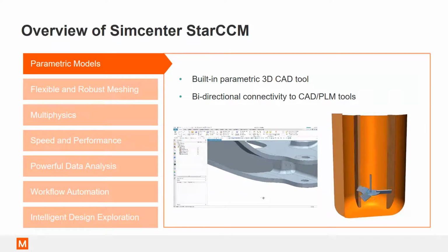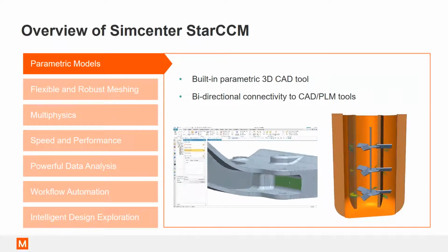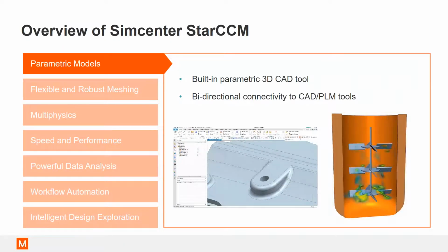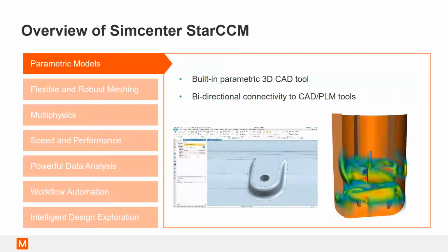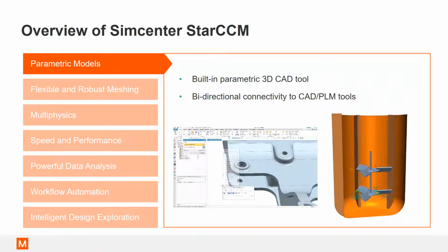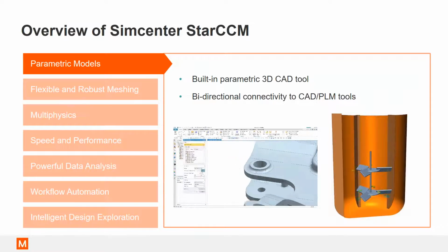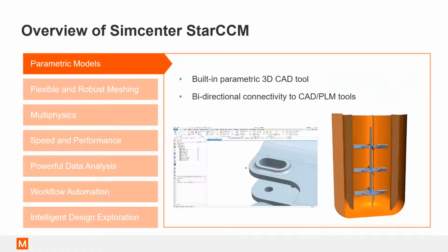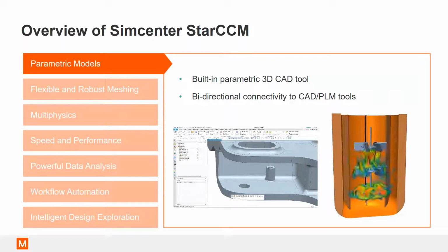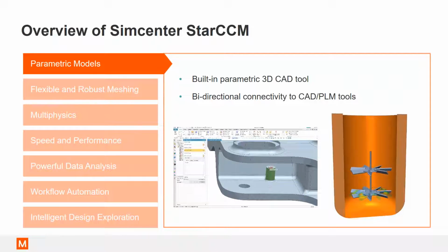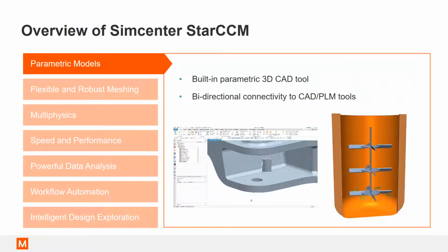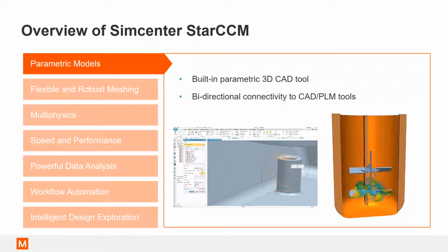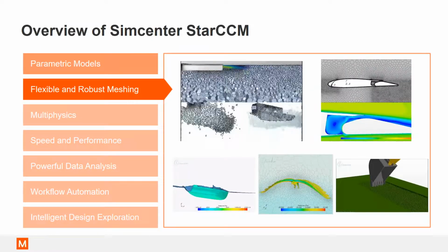And here is a video showing synchronous modeling capabilities in NX, where you can basically import any CAD and perform operations on its surfaces. We will be showing similar features for today's demo. Now, once you've parameterized and imported your geometry in the CAD tool and conducted your simplification operations, the next step would be the meshing. Now, one of the key highlights of CCM Plus is its meshing capabilities.